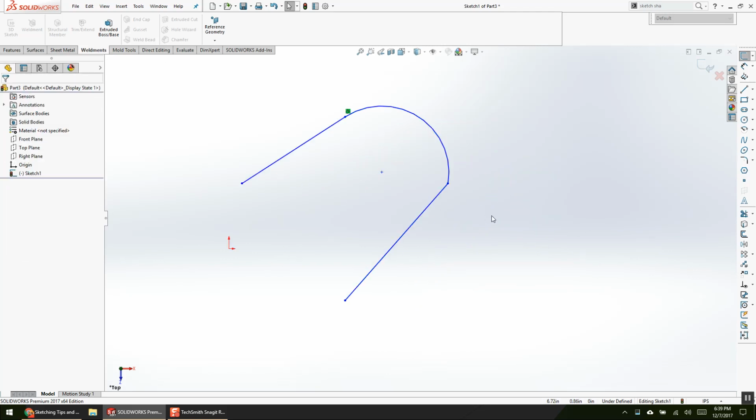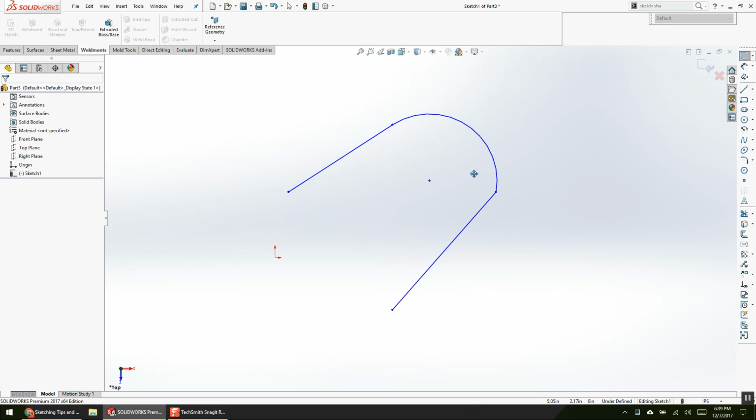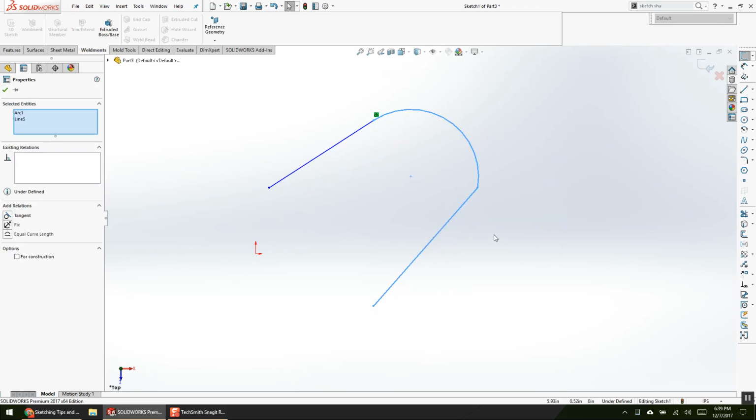Everybody understands the difference between box select left to right versus box select right to left, right? Okay. Yeah. Well, this is not my PowerPoint. These are just freebies, so no extra charge. If I box select right to left, it doesn't matter if I'm top down or bottom up. All that matters is when my cursor starts on the right and goes to the left, I get a green box, and every single thing inside of that box in any capacity is selected. So both of those are selected.